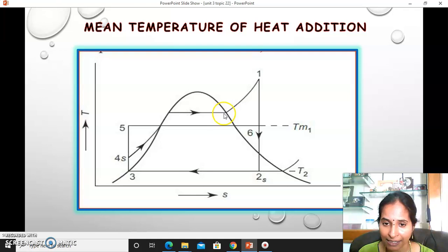When you use dry saturated steam in the absence of superheat, the final end condition of the steam would be wet steam, totally away from the dry saturated line, and also lead to erosion and other issues in turbine blades.